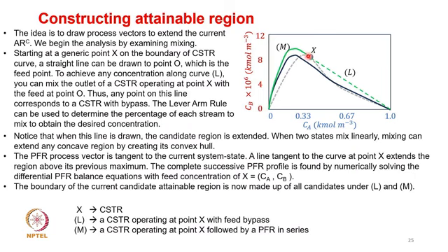At this point it is a CSTR, and you have to have a PFR in series, because this curve, the green curve, corresponds to the PFR in series. So this part of the attainable region is eventually representing the PFR.